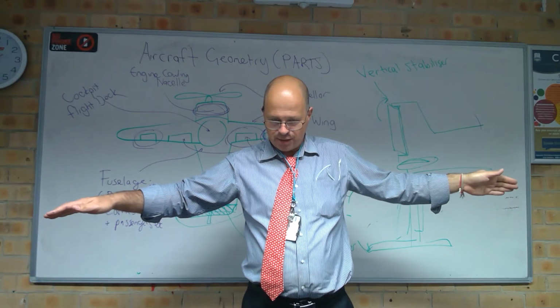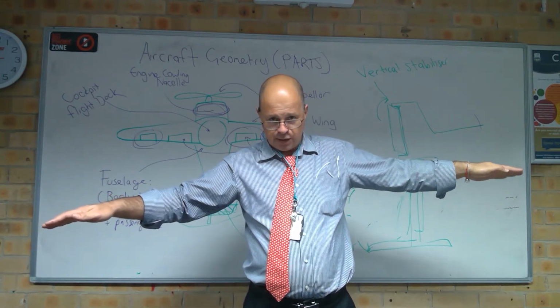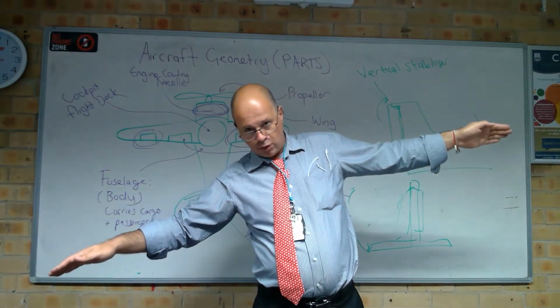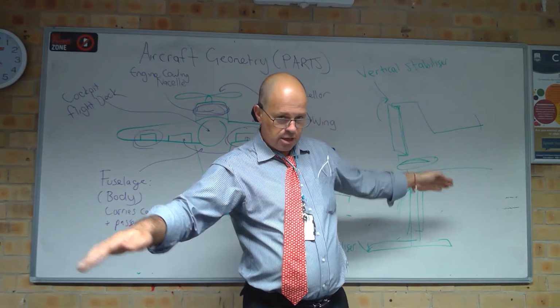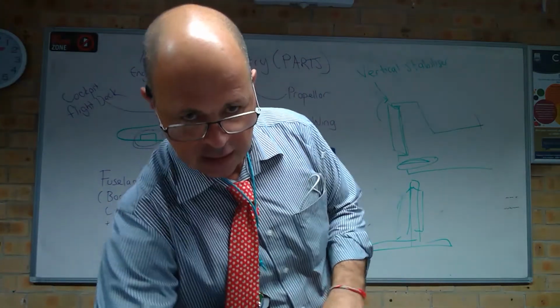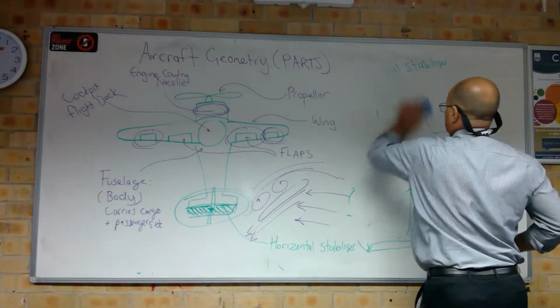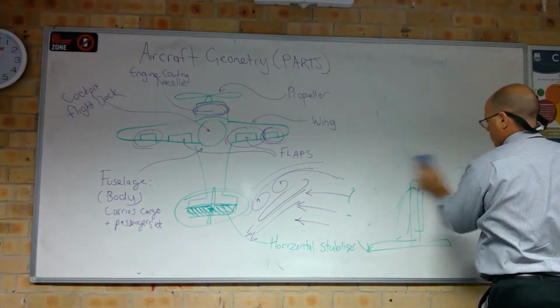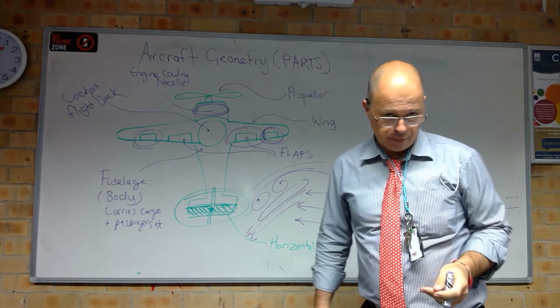It's not as aerodynamic. So when I turn that aileron down, because I want to roll to the right, I'm increasing drag. So I'm going to do this, and that's called adverse yaw. Okay, adverse yaw, just write it up here, is a real problem because when they first started designing aircraft, it's also called a Dutch roll if you're a pilot.